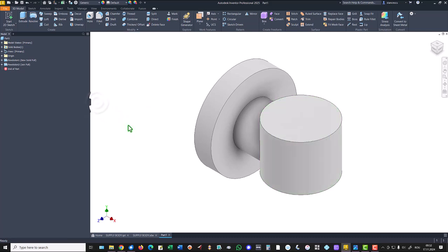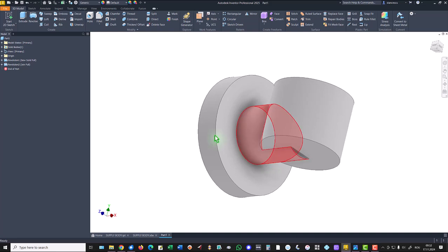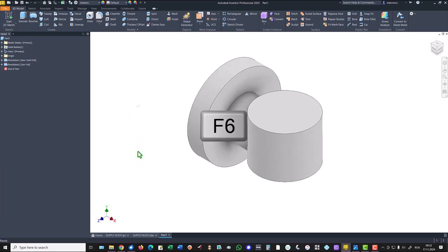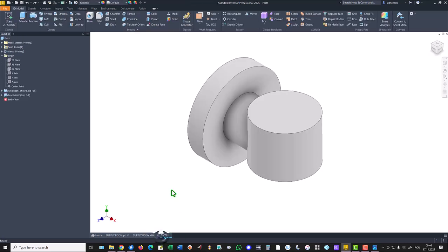Okay, you see here is an extension. We continue with this curved feature. The diameter is 66. Here is the radius 38 for the mid curve, and dimensions 75, 170. We apply sweep.